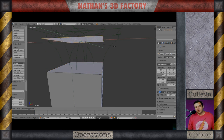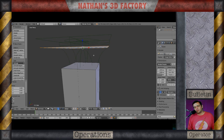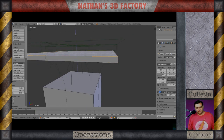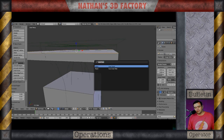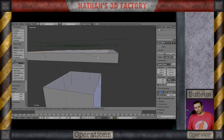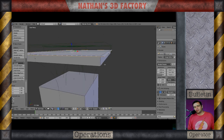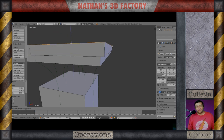Continue with the body. Now this time I'm not going to extrude, but what I'm going to do is duplicate. As I duplicate, I'll bring that upward. So now, I'm going to do the same thing there. I'm going to inset, except I'm going to go the other way. So it's more like an outset, I guess you can call it.